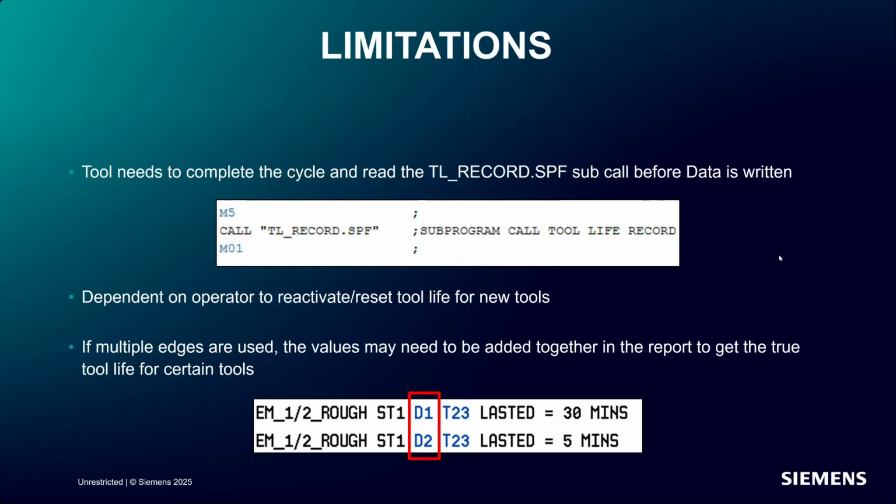The problem with that, and the reason why I didn't show you that and didn't write it to do that, is that it's inherently more risky, right? Now we're talking about changing the cycles of my machine. I'm changing a very important cycle that teaches the tool length of all my tools. If I was to delete something there or skip something that needed to be read and I messed that up, well, next thing you know, my machine is down until I can get somebody in here to give me the original program or whatever.